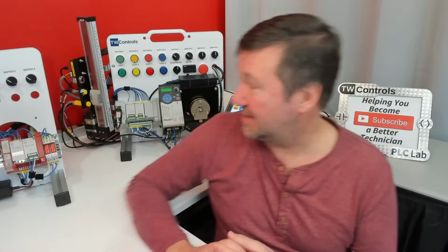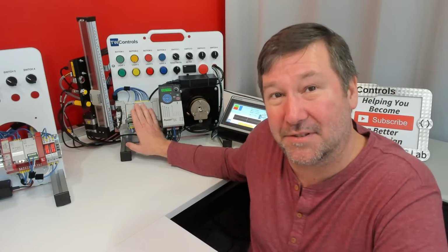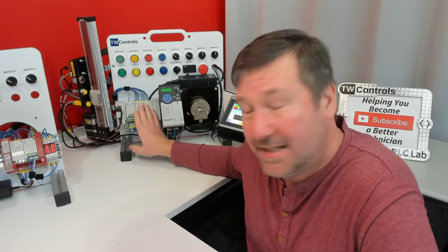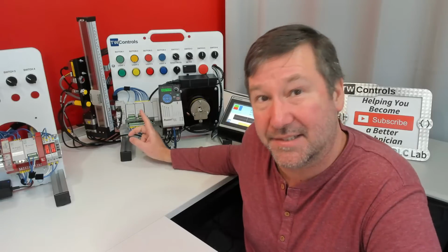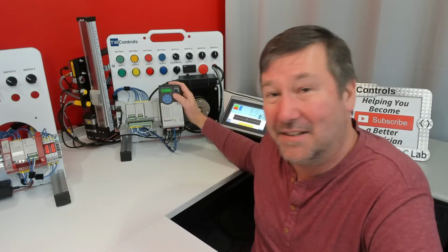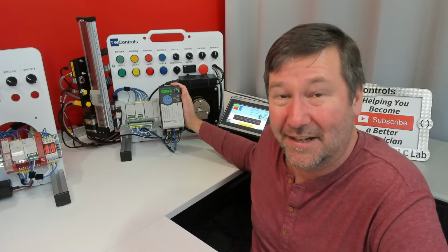Let's see. How can you integrate a PLC with other industrial control systems like SCADA and DCS? Well, kind of going back to the earlier one on, well, I need this over Modbus TCP. It's understanding the language the two commonly speak. So I love the Micro 850 for stuff like this, or in general, is this thing can speak EtherNet/IP. It can also speak Modbus TCP. It can also speak Modbus serial. It can speak the old ABDF1. It can do a lot of cool things, so we can tie it in a lot of different ways. Now this PowerFlex right here over Ethernet, it's only doing EtherNet/IP.